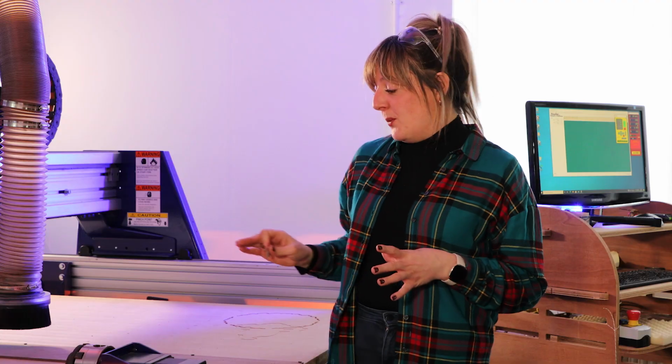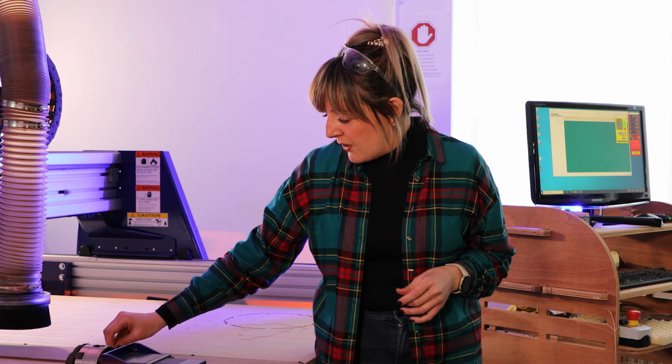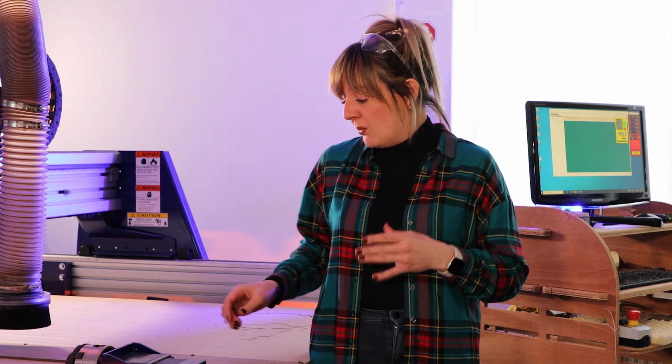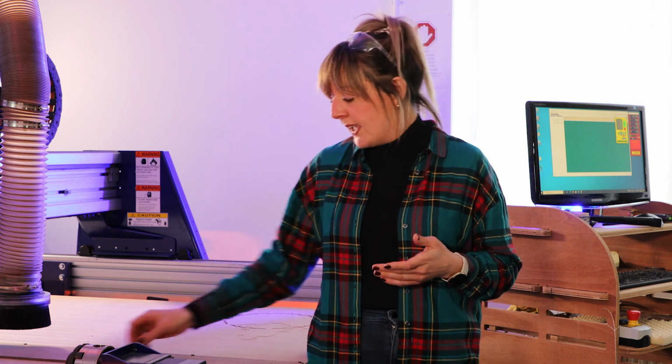So now that we're done with our two test cuts, we're going to check how well this pin fits into those pockets. So for the first one, we actually had no allowance whatsoever. We actually created that circle based on the diameter of the pin that we're using. So really, we'd expect a very tight, snug fit there, which we do have. I'm having to put in a lot of effort to try and push that in.